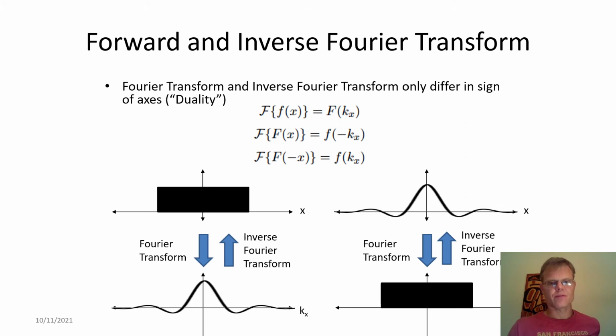If we took the Fourier transform of a function, and we take the Fourier transform again of that function, what we get back is the original function, just flipped in sign. Now with something like the rect and the sinc function, this makes no difference. Flip them around and they look exactly the same.